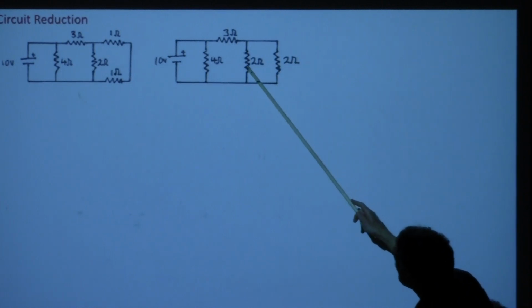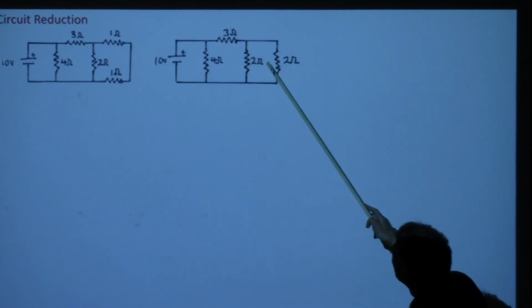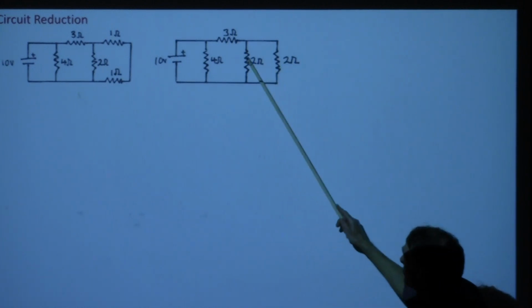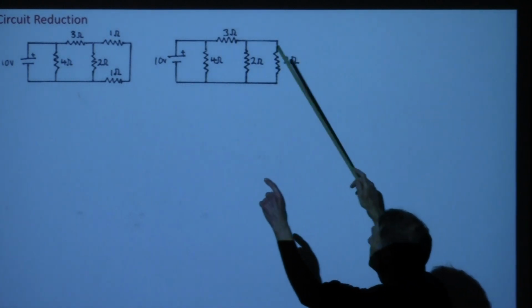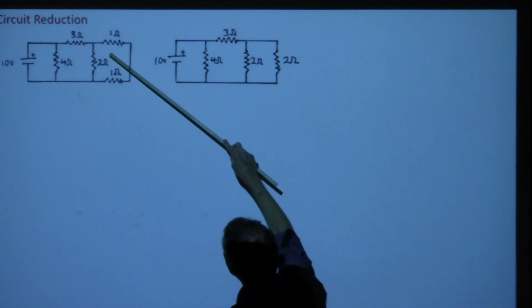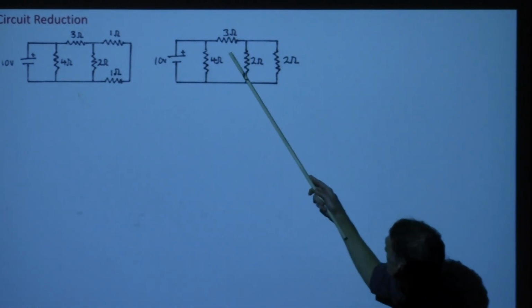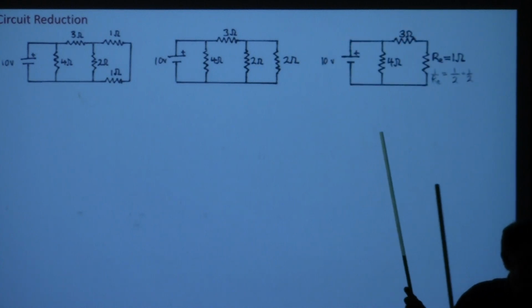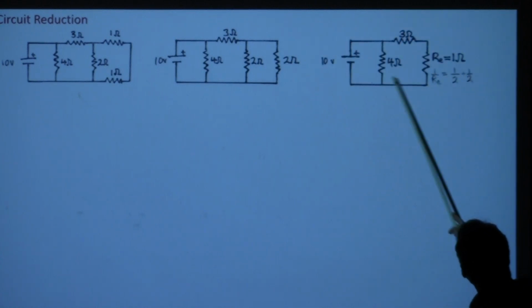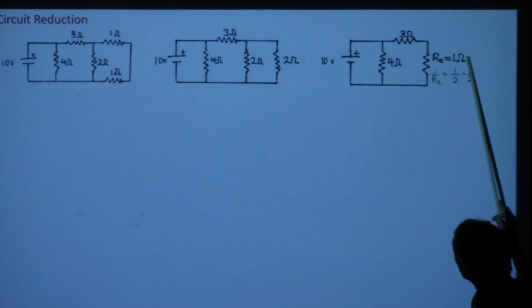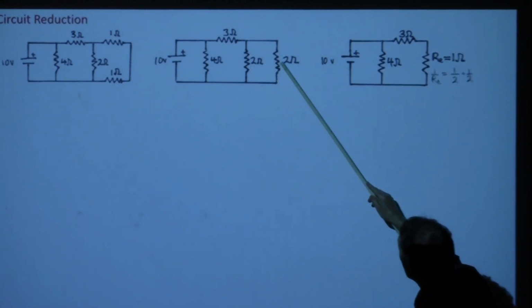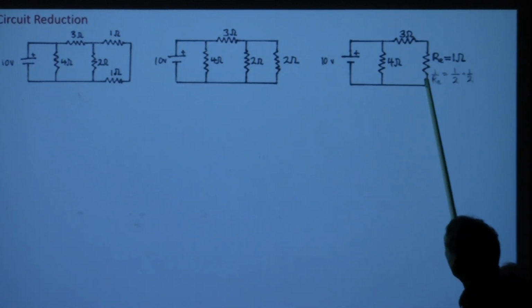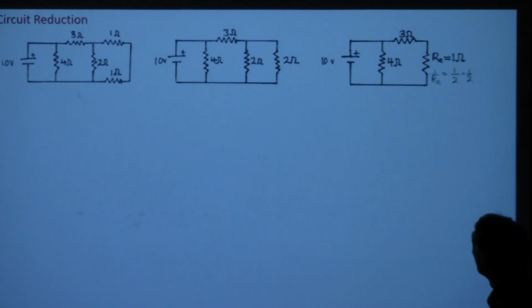Now, are these two in series or parallel? Okay, they're going to be in parallel. I tried to keep the numbers real simple. So these two are in parallel, and let's just continue simplifying this. So real quick, 1 over R equivalent ends up being 1. In fact, if these are the same, whatever you get in parallel is actually going to be less R equivalent. So anyway, you can do the math and come up with 1 ohm there.